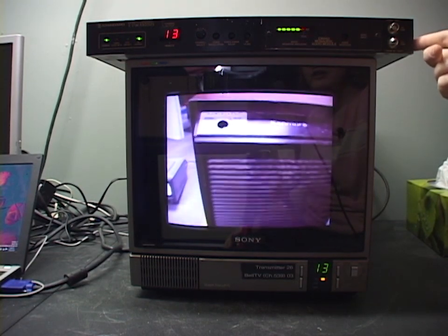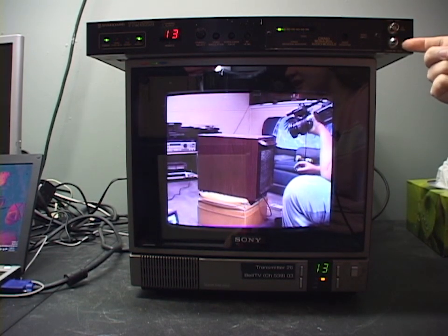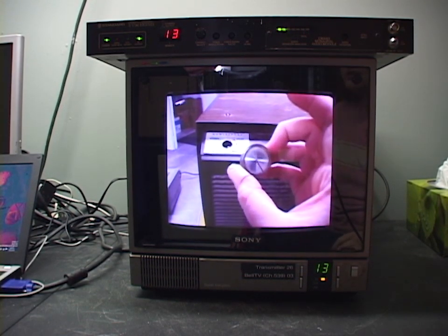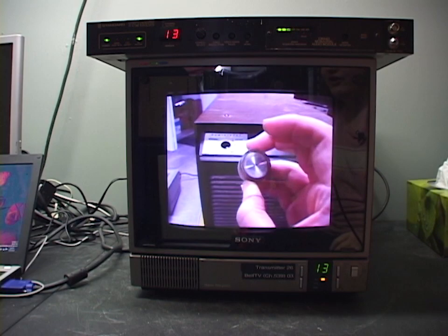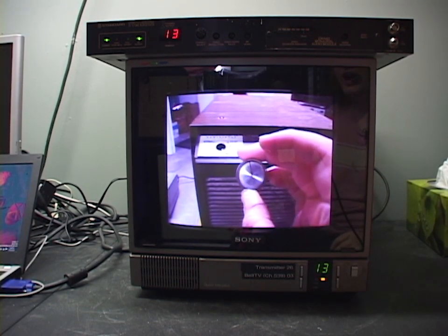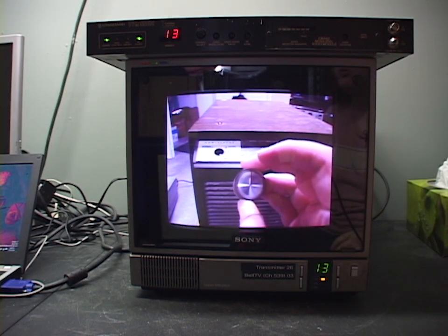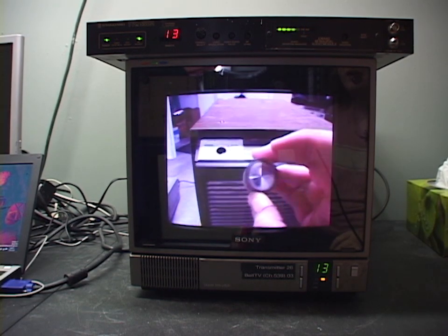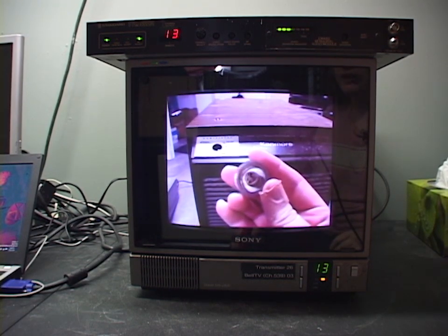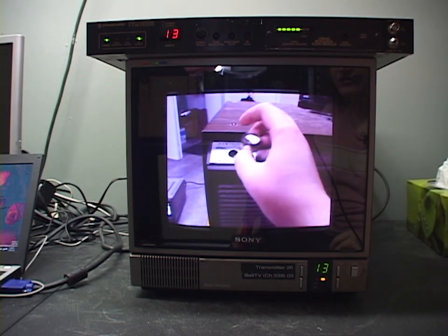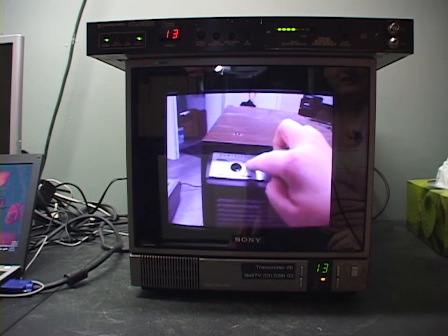And the reason I'm doing that, instead of using the test jack that's already attenuated by 20 dB, is because I don't have an F connector terminator, and I don't know if it hurts the unit if I power it on without anything connected to the main output. So I just figured I'll attenuate the main output and plug the TV directly into it.